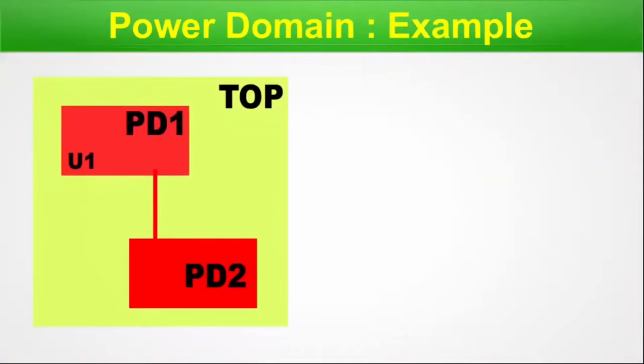Here, the picture is like that. There is a top. Okay, let me bring my mouse pointer here. This is the top block. Here, we have E1 and PD1. And inside that level, we will create another PD2. That is, this is power domain 1. This is power domain 2. And I again emphasize that your HDL and your power intent are going hand in hand and in parallel, as we have pictorially described. So, let's bring the example.